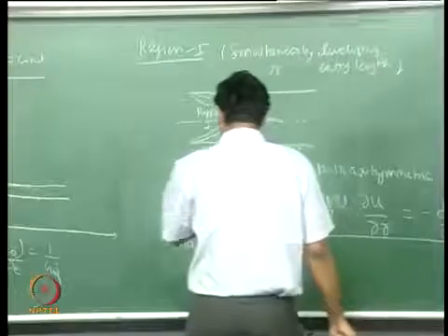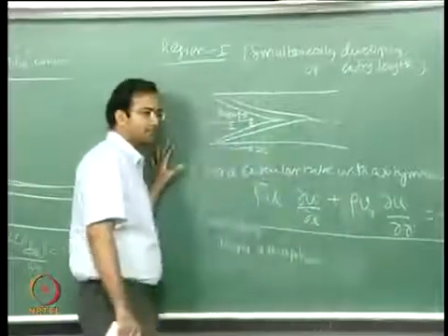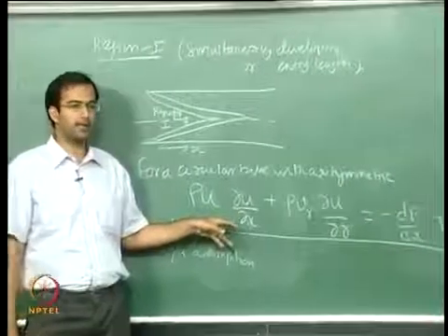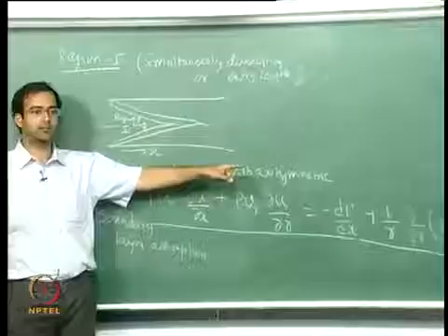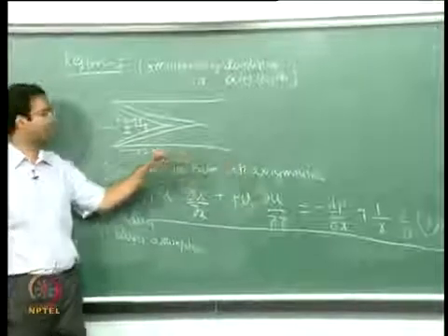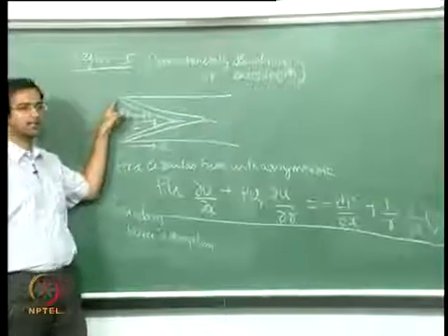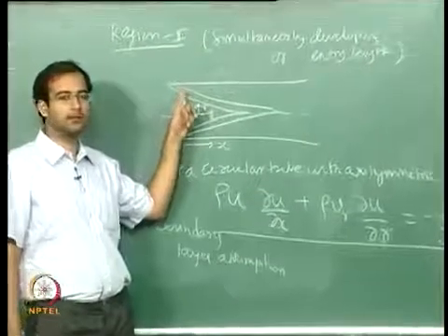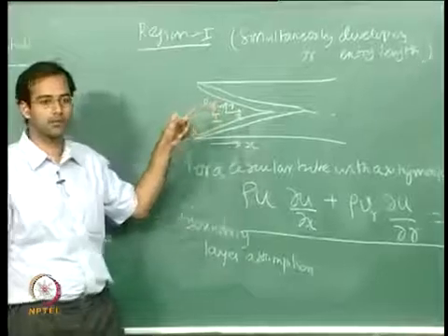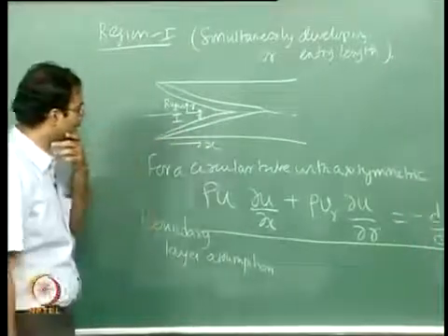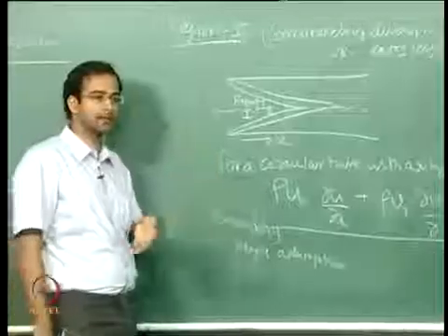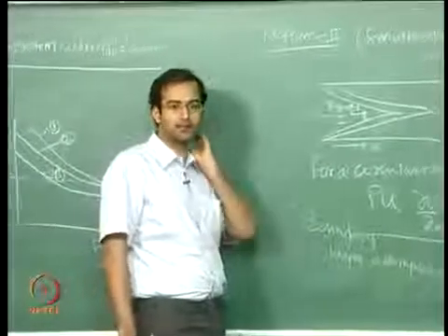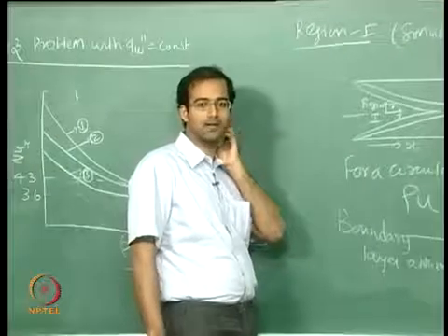So this is an assumption to the actual problem, because what you are doing here, you are neglecting d square u by dx square. So that could be important, because the acceleration in the x direction is important, and also the higher order derivative d square u by dx square becomes important, which you are neglecting here. And also, since it is 3 dimensional, you could have 3 dimensional effects if you have a non-circular cross section. So these are also not taken into account.